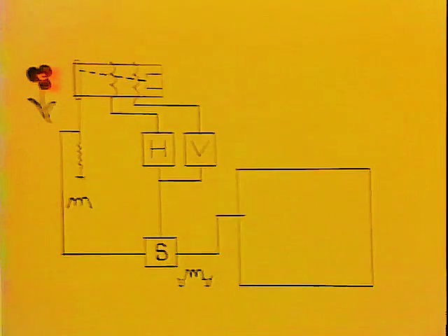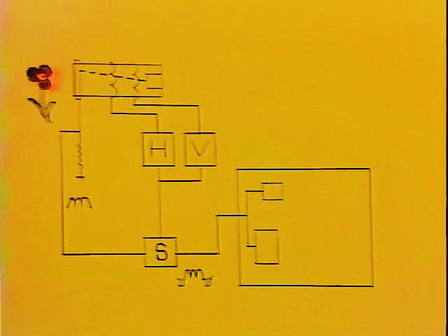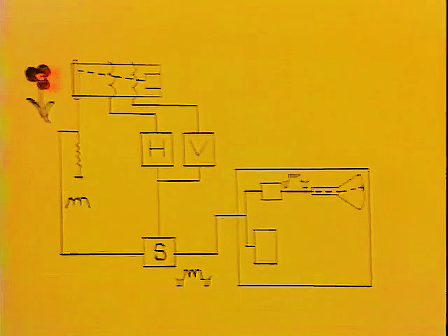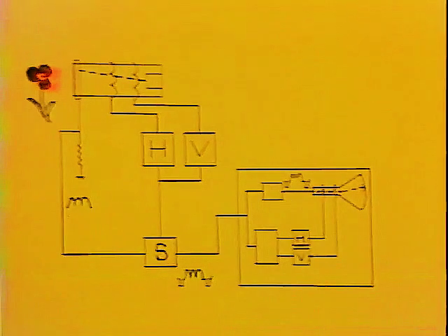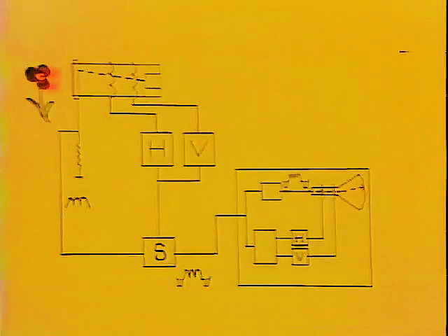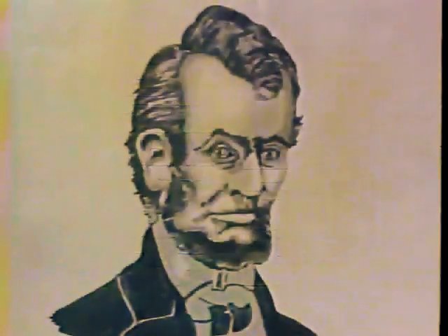The composite video signal enters a monitor or television set. Here, the sync is separated from the video signal. The video and sync are used to vary the brightness of the beam and so produce a picture on the face of the tube. The sync pulses are used to drive the coils around the tube neck, which cause the beam to scan the face of the tube. The result is an electronic picture written on the screen, which is a faithful reproduction of the original.